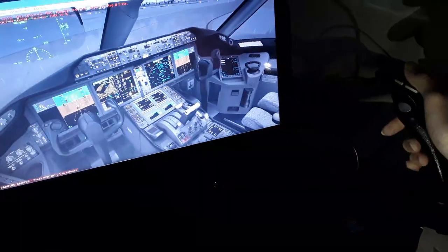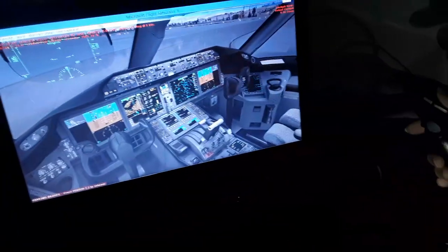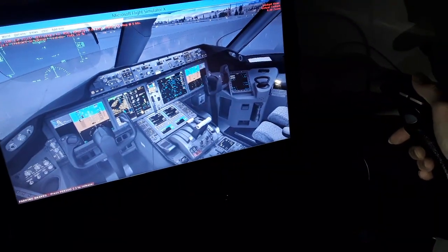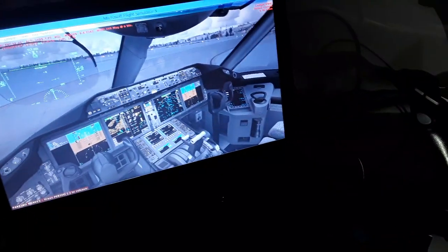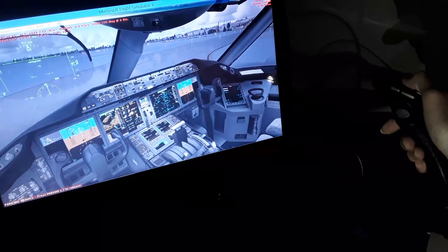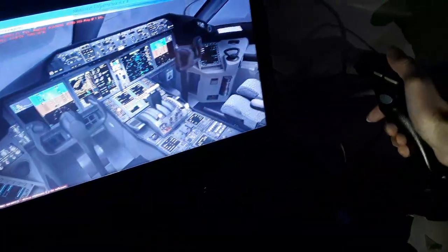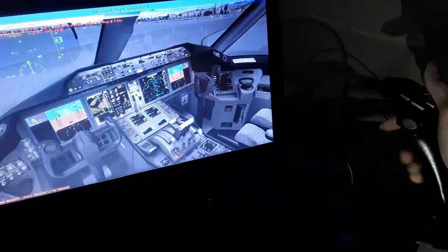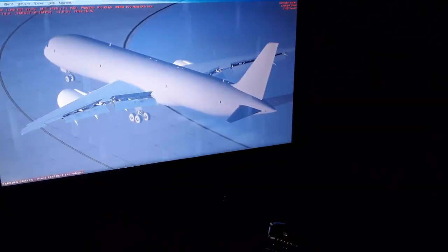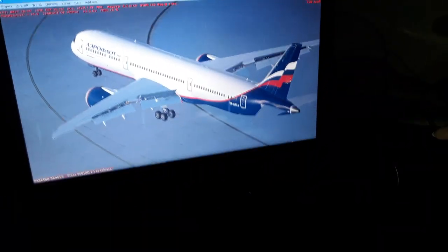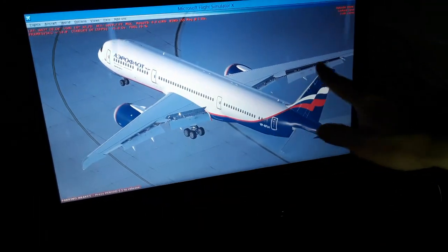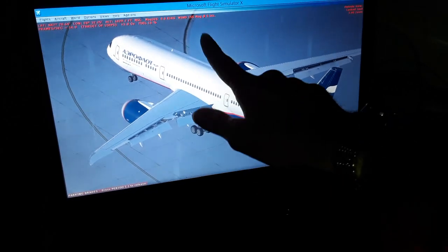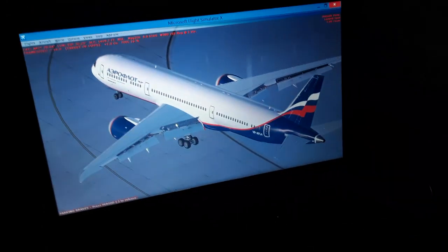So in the Airbus we move the side stick forward, or the yoke forward, to lower the angle of attack of the aircraft, and also apply thrust forward to increase the airspeed. This is the move for stall avoidance in the air. So we need to avoid stalling the aircraft wings. So this is the mean aerodynamic chord. Also here, as I told you, is the fuel, the left and right wing fuel tanks. The center tank is at the center of gravity, approximately through the mean aerodynamic chord.